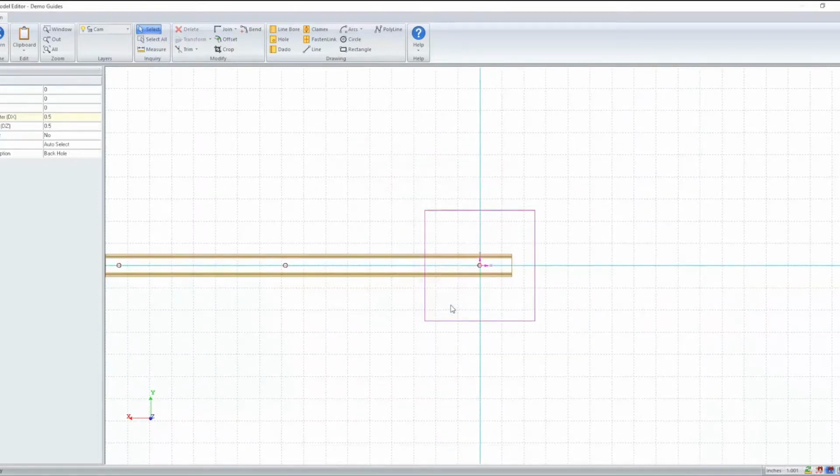Now we can go ahead and add our operations for the spacer block itself. Keep in mind that your drilling configuration may be different depending on the block you are using. So the first thing I'm going to do is select an operation, and I'm going to copy it. And then I'll paste it. The reason why I do this is it just makes it a little bit easier, so some of my parameters are already in place. I am going to switch over to be in metric.